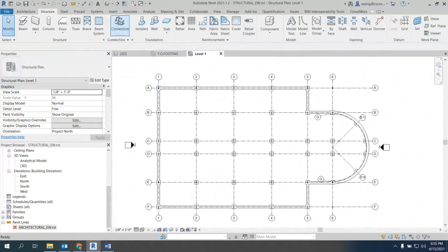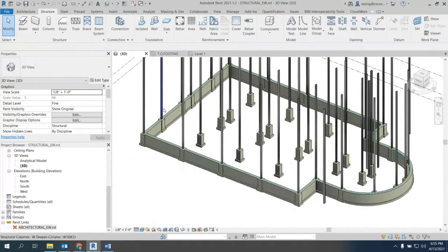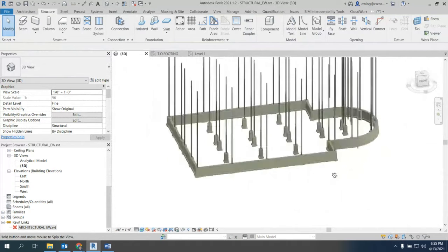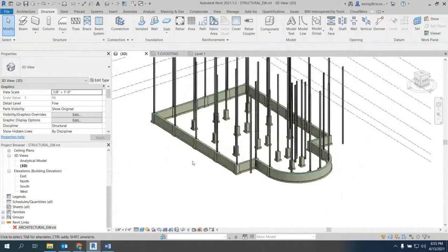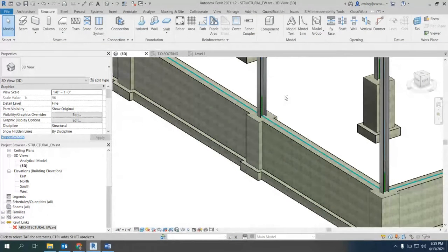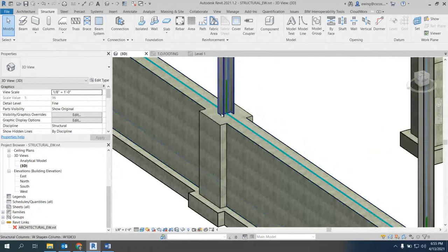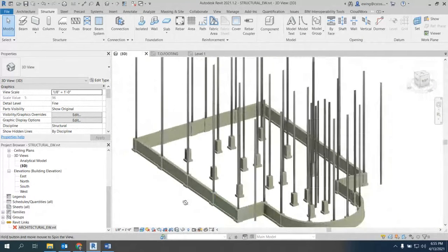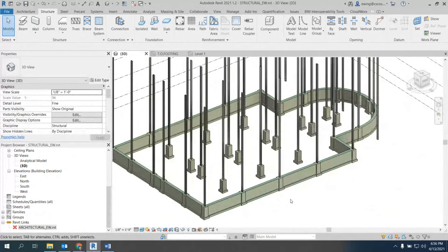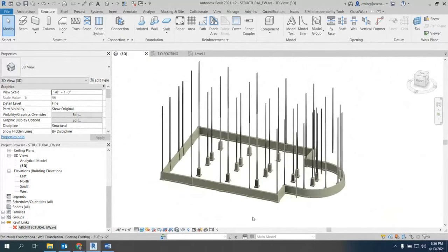Okay, so let's go to a 3D view. Look at that, we've got columns. We've got a few extra again. You can clearly see which ones are wrong. Now you can see how Revit is working, and how basic structural engineering works. There would be a base plate there, but we're not going to get into that. You see that force is aligned with all of these lines. It's going to go straight down, and it's going to move that gravity load into the ground, where you want it, taking it from start to end.